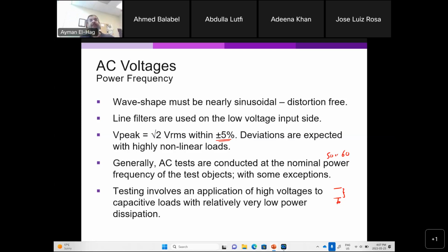If we talk about a cable, when we model the cable, it depends on what type of study you are working on. We can model the cable as a resistance in series with inductance, but that is if you are interested in seeing the power loss in the cables, and you want to see what the copper loss is if it's subjected to full load or half the load. That's a different test. Our interest is to see if I apply a high voltage between the core of the cable and the shield, can it withstand the high voltage or not. So I'm testing the insulation. The way we look at it, the asset is a capacitor.